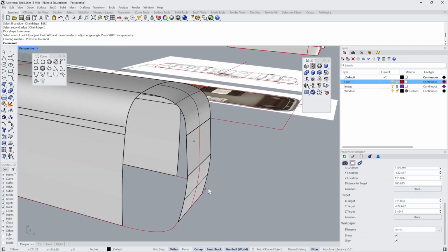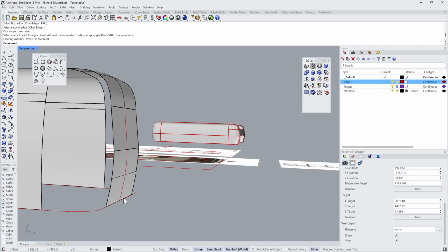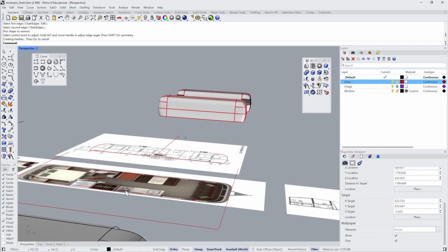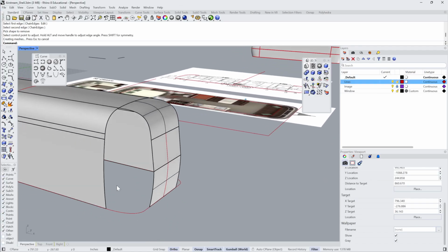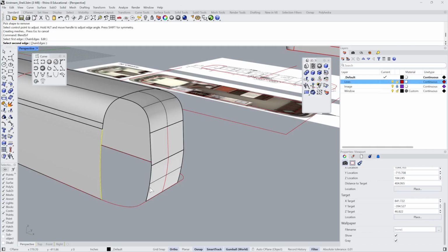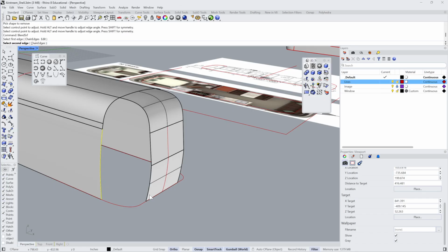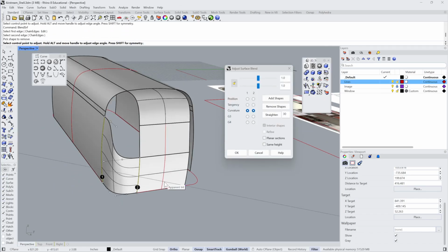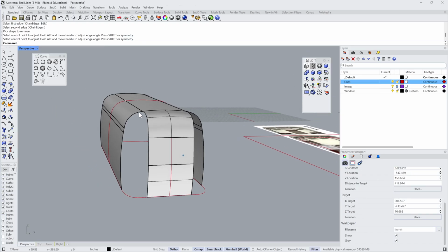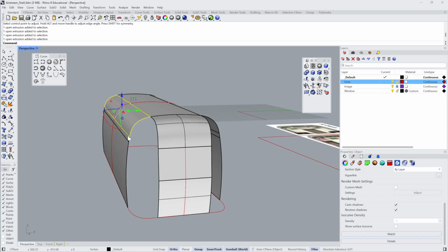Okay. Now, this is great for showing us a basic footprint of the Airstream, but we also have this other panel with single curvature here, and we're going to use blend surface again. But you can see here that that's going to give us weird results, right? So this is where we have to start strategically cutting our curve up. And this is where it wasn't so helpful that I drew this curve in multiple pieces.